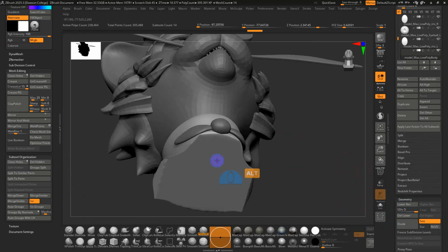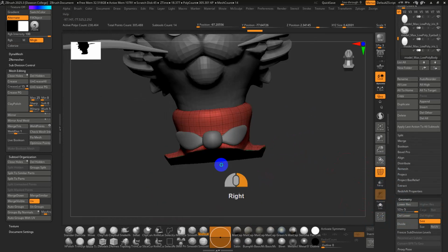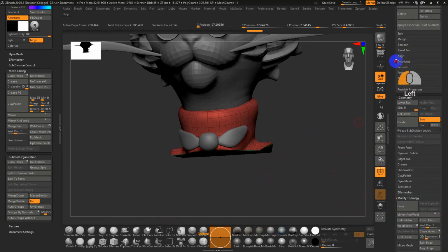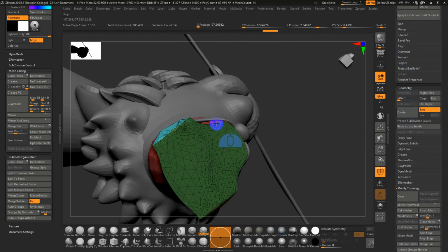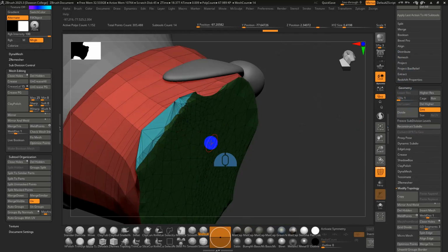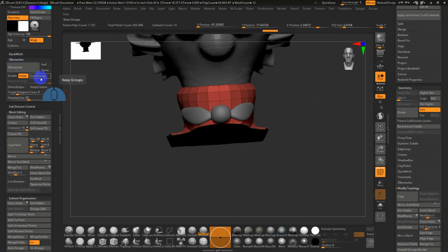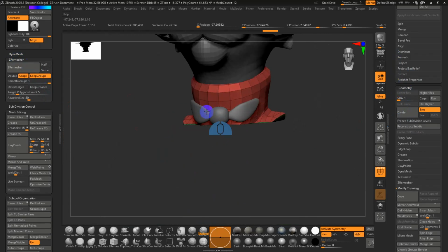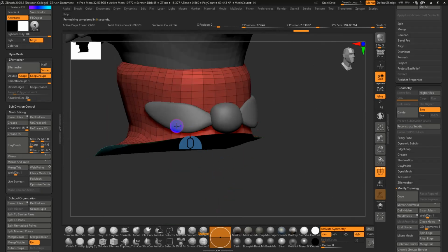Yeah, there is some awkwardness with the wireframe. So you can decide if you wanted to. I might just go back to low res for a second here. I'll just go back to division level 1. Because of my slicing, my trim tool, I've got different polygroups. So I could just say, okay, let's maybe Z-remesh this thing quickly. I'll say keep groups. In this case, I'll probably just turn on symmetry for the model. And I'll say maybe we'll keep it the same and remesh.